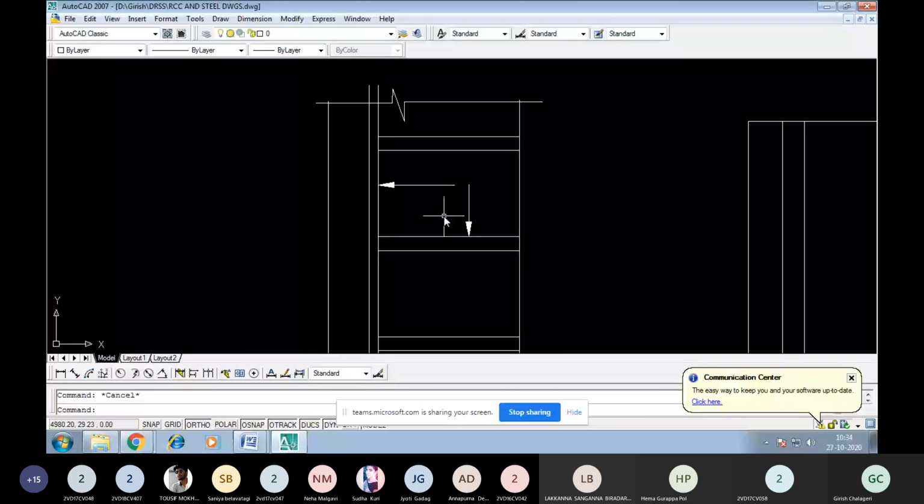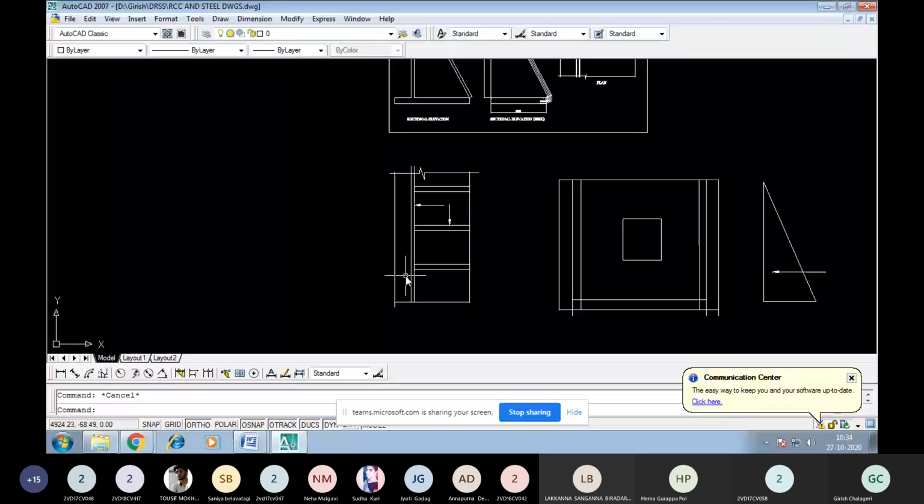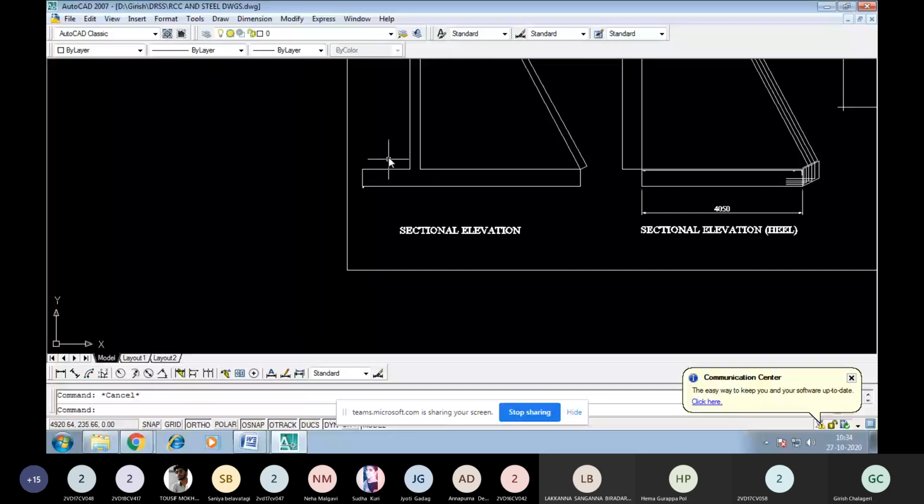This is what we can see in the counterfort design. So the heel slab as well as the stem will be designed as a slab with WL square by 12 moment maximum at midspan, and at the end supports where it is connected with other structures, the moment will be WL square by 16. Then we are going to design the toe. The toe will be designed as usual here. The pressure we get on the toe side will be in this fashion. Downward force.